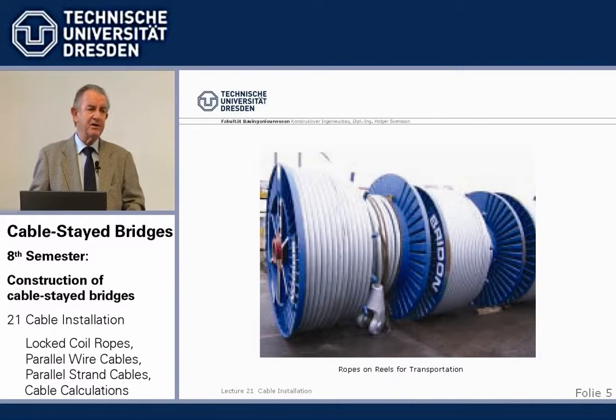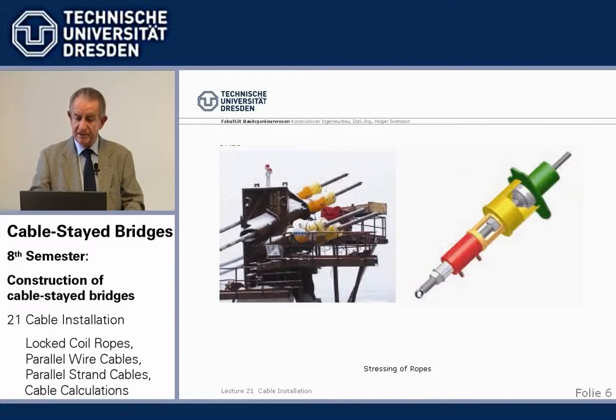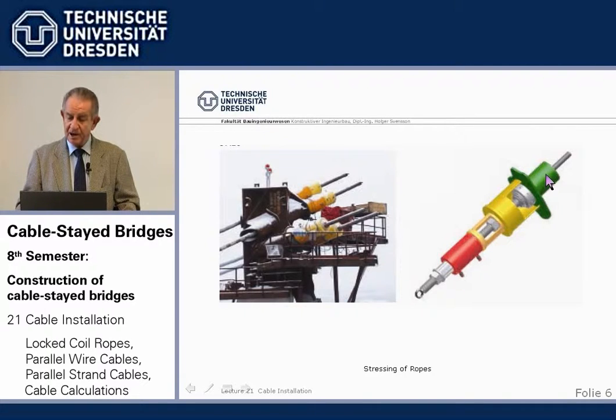They are, as I say, completely shop fabricated, and they are transported to site on reels with a considerable weight if they are long and thick. And they are stressed basically by a hydraulic jack, and the connection between the hydraulic jack and the anchor head is done with a pull rod or tension rod, which is screwed into the anchor head and is screwed into the hydraulic jack, and in between there's a support nut.